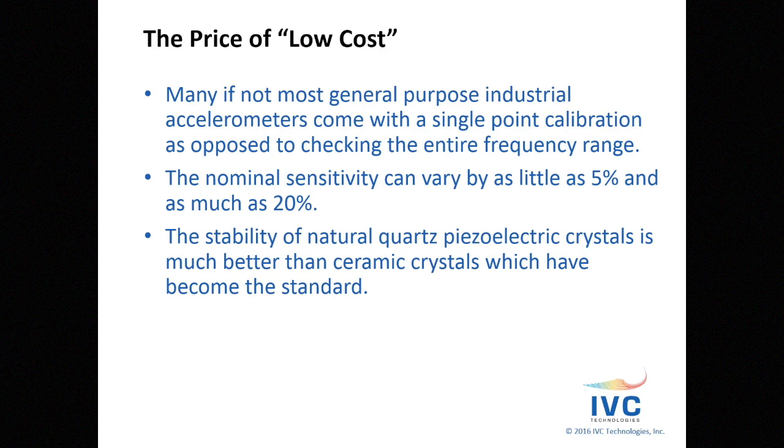The stability of natural quartz piezoelectric crystals is much better than ceramic crystals, which have become the standard. There's a lot more control as far as the wide range of sensitivities with the ceramic, but again, they're much less stable, so if you drop the sensor, it's much more likely to get knocked out of calibration. And again, you're back to taking garbage data.